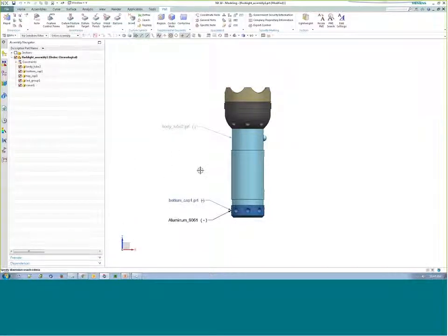You can imagine if you have a part that has some very tight tolerances and you want to determine how to make that part a little bit cheaper to make, for the benefit of you and your manufacturing partners, for example. You can search to find out what's driving up the cost in an assembly or in a part. And a manufacturer could search and identify where the tolerance has been specified and what kind of tolerances there are. So that's another feature of the PMI tools in NX, being able to do this searching and reporting of PMI elements.